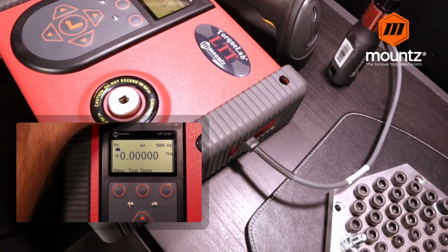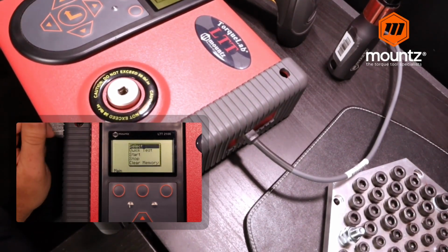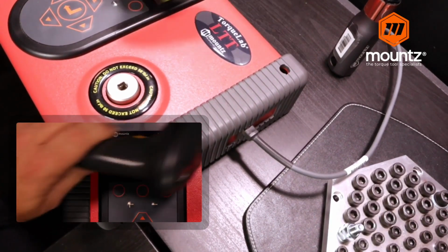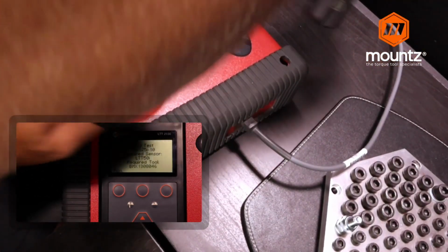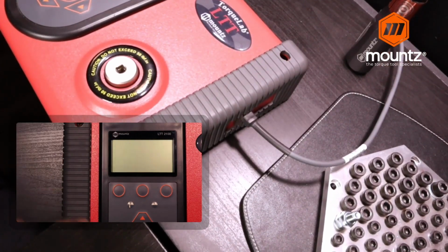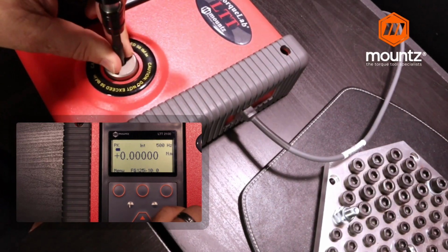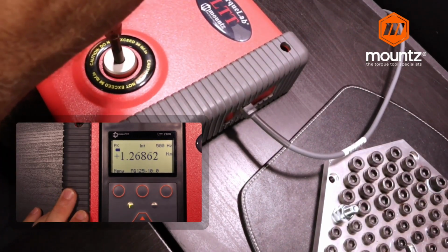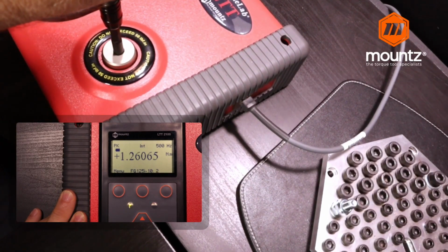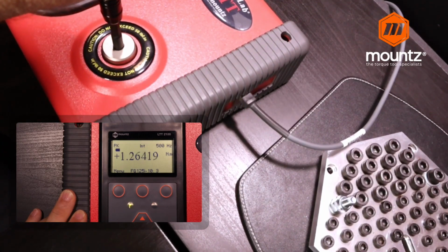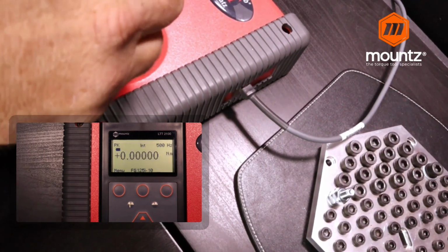So there's another way that we can do that, and that would be the use of a barcode scanner on a particular tool. So if you want to go out to the line with the unit for the built-in transducer, in this case we can use a barcode scanner in our tool test function. So we go ahead and enable the tool test function. That gives us the ability to scan the tool. It will automatically pull up the limits and the test criteria for that tool. It will take the particular readings or number of readings that we have set up for that tool. In this case, I think we have 5 set up for this test. And then after the 5th reading, the unit will go ahead and reset.